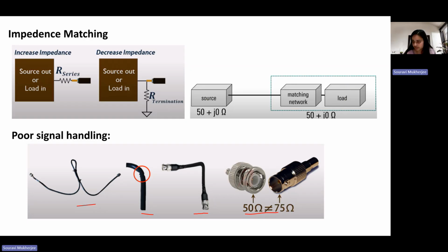And transmission line effects also come in when you have long distance transmissions. The fact that you have this finite R, L, G, and C can result in loss, as we saw, right? There's a non-zero alpha, that means there will be attenuation. That disturbs transmission at longer distances. So you have to have constant impedance matching and changing of the transmission lines accordingly, or make up for that with much higher voltages so that you get transmission to a much longer distance.